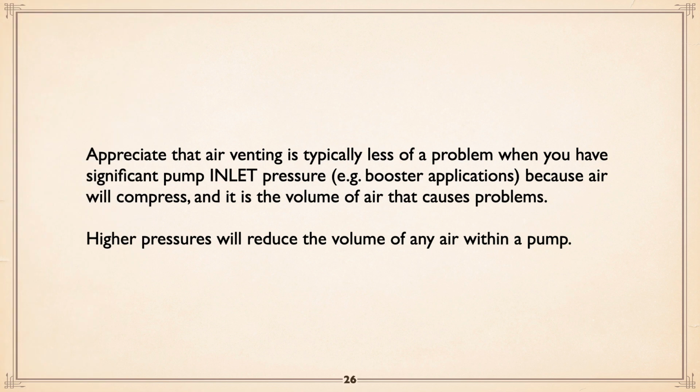Appreciate that air venting is typically less of a problem when you have sufficient pump inlet pressure, like boosters, because air will compress, and it's the volume of air that causes problems. Higher pressures reduce the volume of any air within a pump. Basically, air being compressible, if you have high pressures, any entrained air is usually not a problem because the volume of the air is quite small because of the high pressure. So for what that's worth.